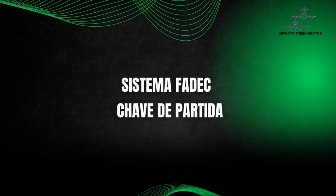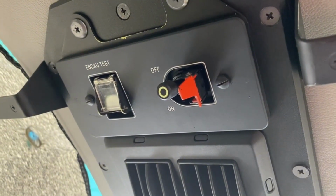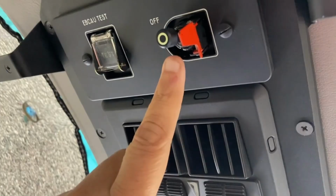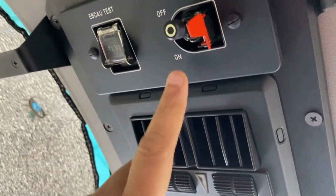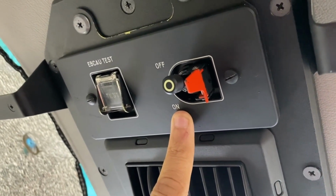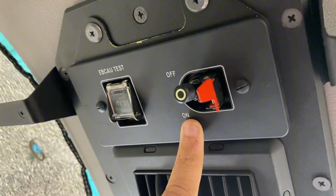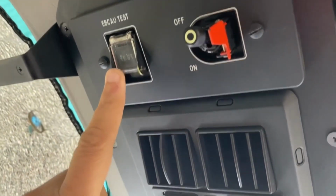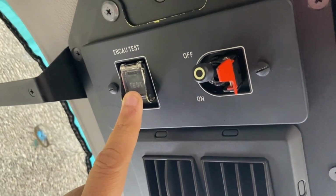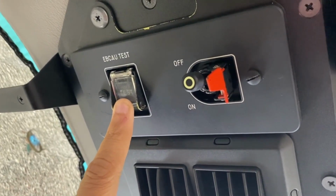Now guys, another important signal that is transmitted directly to the DECU and then over to the FADEC computer system is the signal coming from the start switch itself. Off, on. When you set it to on here, it's a signal to the digital electronic control, the DECU of the FADEC system for starting the initial start cycle of the helicopter. And here we also have a test switch to perform maintenance tests on the helicopter. I'll show you a video of how to perform this helicopter test.